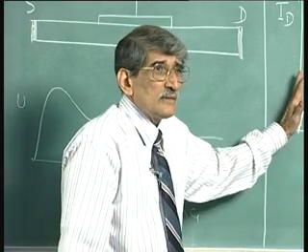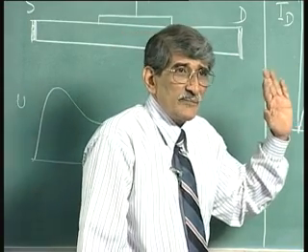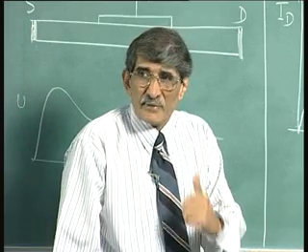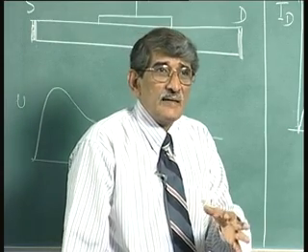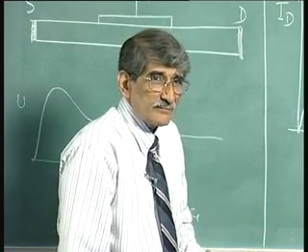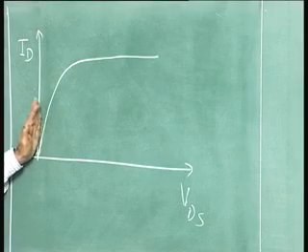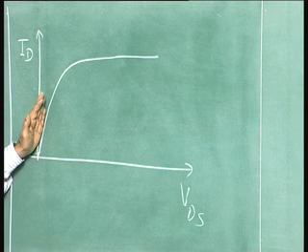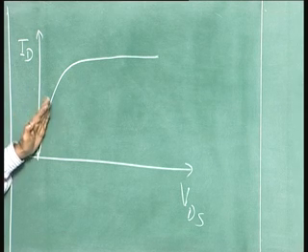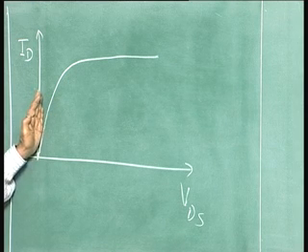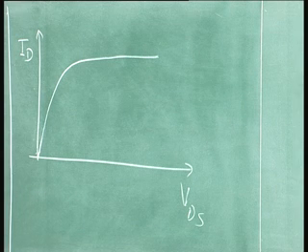Right now, gallium nitride is not for high speed devices, it is mainly used for high power devices because of its high band gap, better thermal conductivity, etc. Similarly, silicon carbide. So, this region can be controlled very easily, or it is much better with gallium arsenide. You will see soon how to get even steeper with the high electron mobility transistors. That we will see in a couple of lectures later.